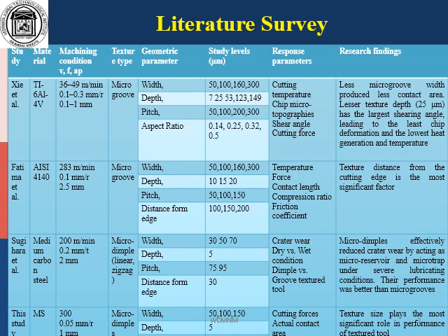The display table shows a summary of some of the notable scientific material referred to while conducting the literature survey. As can be observed, among the most research findings, cutting tools with microtextures on the cutting face have shown notable improvement in reduction of wear, cutting forces, and friction. However, these benefits entirely depend on the various parameters like width, depth, pitch, distance from the tool edge, etc., considered for the microtextures.